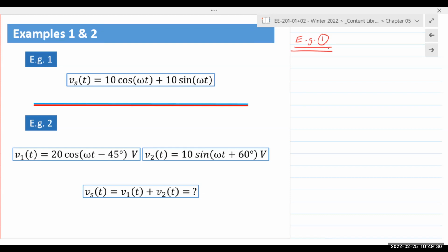That's also the principle behind noise cancellation technology. Noise cancellation technology uses a microphone to capture surrounding noise. So you'll have multiple frequencies that are captured using that microphone. Then you have an inverting amplifier, which inverts the phase by 180 degrees. Magnitude is kept the same, and you add it to the same incoming signal.